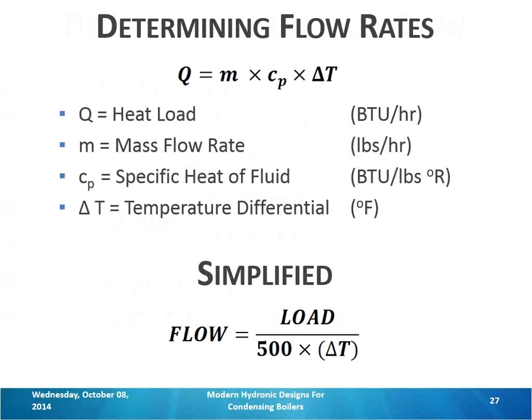Then we design our boiler plant. This just looks at basically the mechanical space. We have 3 high-mass, high-volume condensing boilers, set up reverse return with motorized isolation valves. We have return and supply temperature sensors, and we have a variable speed pumping package.